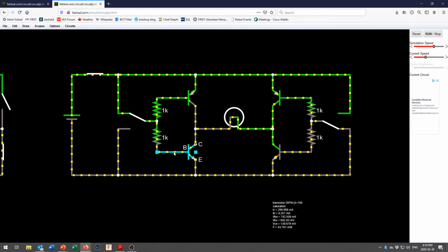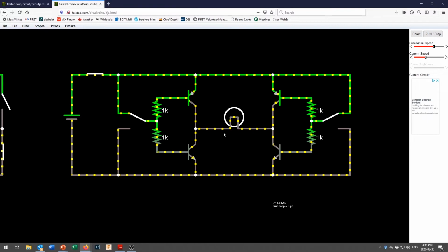Now, there are a few things that we need to watch out for when we're hooking this up. And one of those is that voltage spikes can sometimes happen. When the motor is spinning, that big flywheel inside, well, it's not a flywheel per se, but that rotor acts like a flywheel and it stores lots of energy. So when I turn the motor off, that stored energy inside the motor still has to get out. And it's not just the mechanical energy of the spinning motor, but it's the electrical energy of that magnetic field that's been built up around the coils. And that's something called induction.